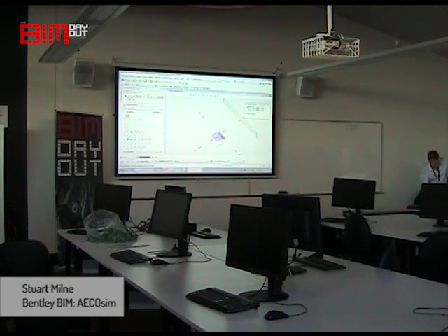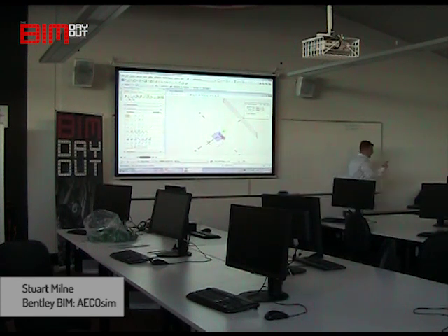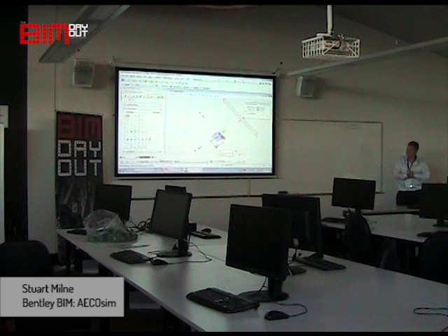Now, let's say, for example, I wanted to come back in this direction, and I did not know what that distance was there. How do I then make that snap perpendicular to that point there? Well, what you do is you hit enter. What enter does, it actually locks you into that axis that you're on and won't let you move, which means you can hover your mouse over this point down here and it will not change off that axis. So it's going to snap to that point but not move off the axis. You can click, and then you can finish off this square by coming back to the beginning.